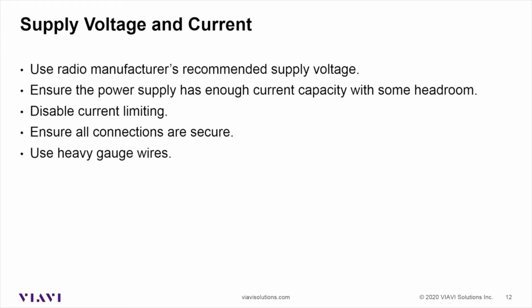And I know sometimes I joke about that, but I've actually had situations where customers have been set up that way. They have a high power radio and they'll be using real thin wire because that just happens to be what they had available to them in the shop at the time. Ultimately, we fail the radio because we can't get the power high enough with that much voltage drop through that wire. So make sure your wire's good, heavy, and the connections are also up to par.